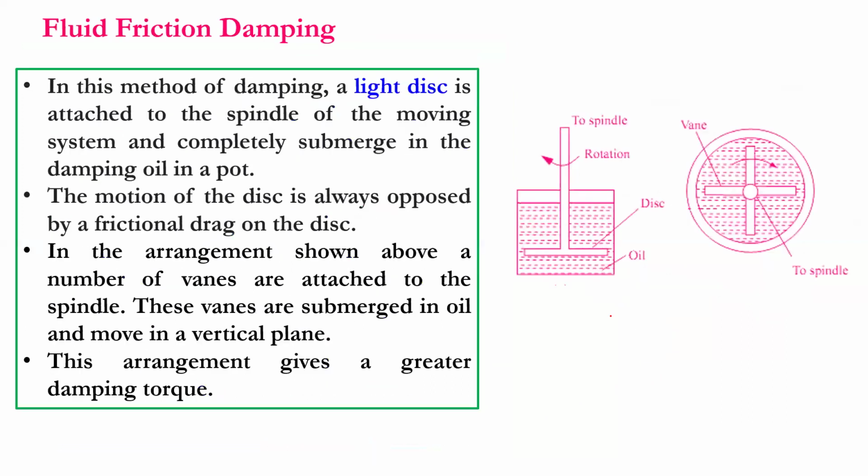Same thing. In order to fill that air chamber, I can fill it with some oil. Due to the viscous nature of the oil, when the spindle presses here, the viscosity will oppose it, and the oscillations will damp out. This may be called fluid friction damping.